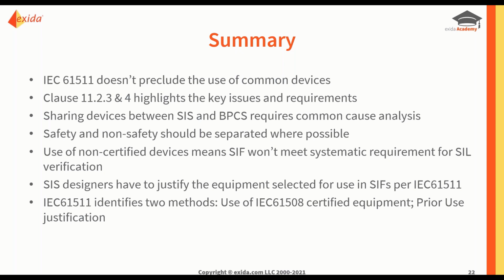All right, so to summarize then, even though 1511 doesn't preclude the use of common devices, we have to pay particular attention to the requirements in clause 11, specifically 11.2.3 and 11.2.4, which highlights these key issues and requirements. If we share devices, then we have to do some form of common cause analysis and make sure that the dangerous failures are going to be sufficiently low enough not to cause us a problem.